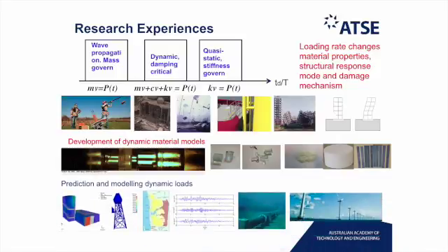Also modeling shock wave propagation and interaction with the environment to model blast loading, ship impact or vehicle impact to model impact loads, and doing probabilistic seismic assessment to predict seismic ground motion. Current work includes predicting the ground motion at the subsea level, not on the ground onshore. It's offshore ground motion.